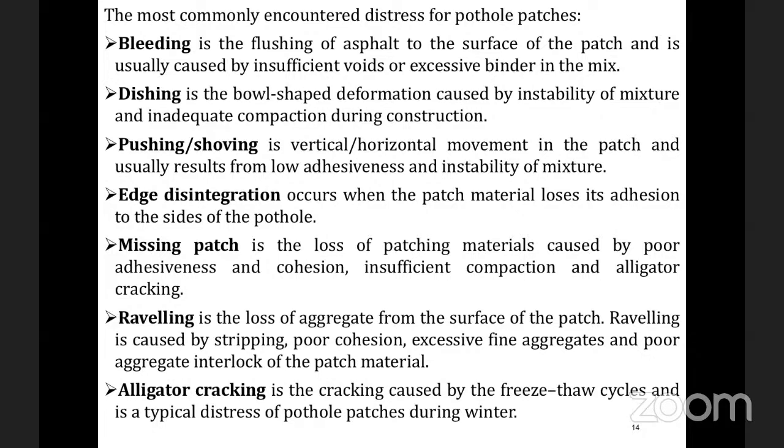And why does it happen? It happens due to lower adhesive property and instability of the mixtures. Next is the edge disintegration that happens at the edges. Why does it happen? When the patch material loses its adhesion at the sides. Whenever we put the patching mixture in the pothole, we have to see that the edges are also properly compacted. If the edges or the sides of the potholes are not compacted, there will be loss of the material due to the adhesion properties.